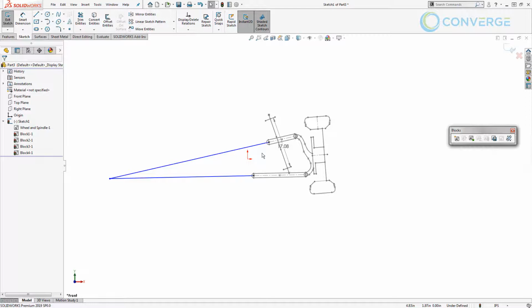If you are going to have those changes in 3D, essentially, if you're going to have the tire move up and back at the same time, and you're going to have those changes in caster and camber, well, then that's something that you need to account for in another sketch block from another view. So you can look at that from, let's say, the top view or the side view, and see how those things adjust in different planes and different views, and help really just drive the overall design and understanding of it.